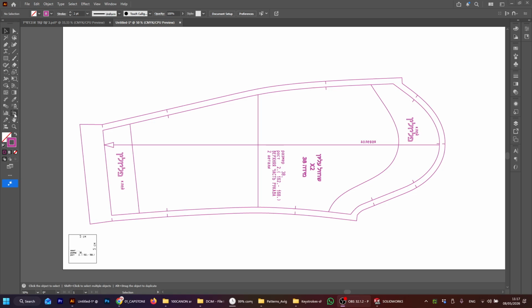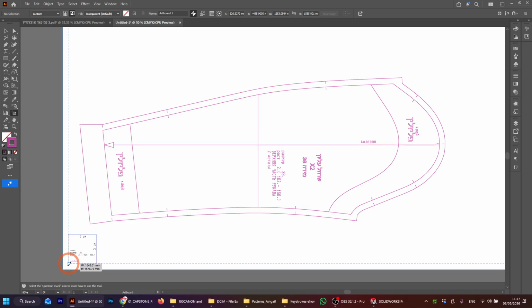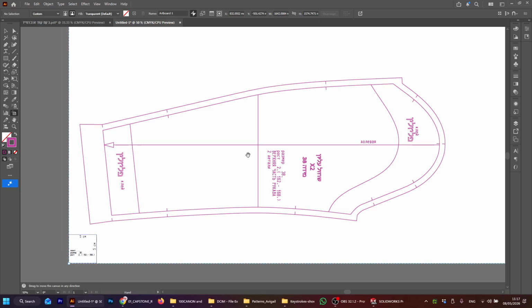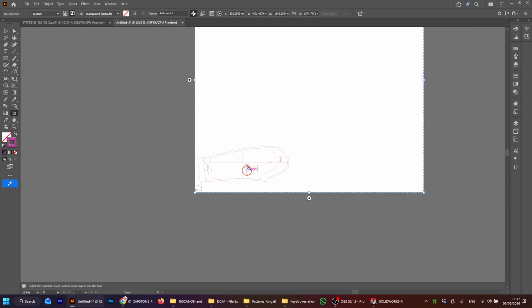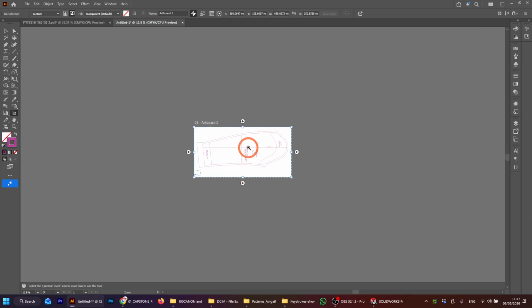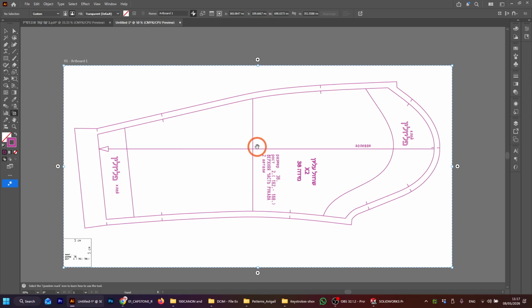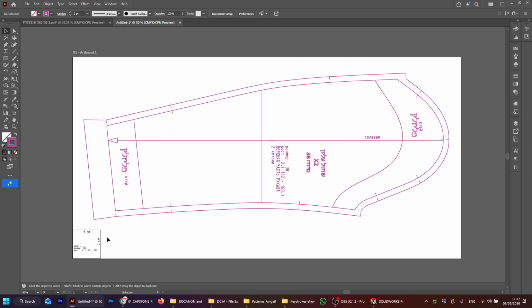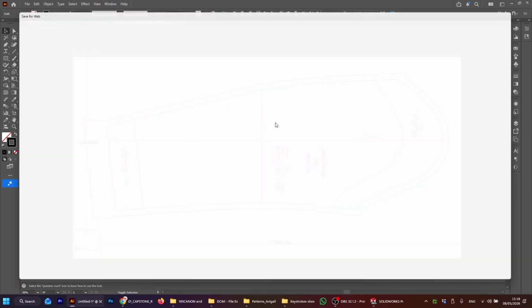So I can use the button to edit the artboard, and then I can move and put the artboard exactly on the edge. Then I can bring the other side of the artboard and put it here. Again, because like they say, trust but verify, I use this transform to double check that I'm still at 5 by 5 centimeter or 50 by 50 millimeter. Okay, I'm good. Control Shift Alt S on the keyboard.